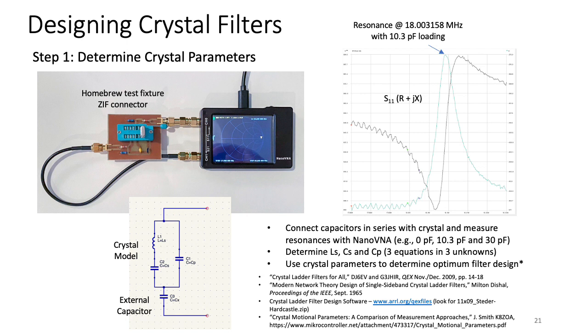Here's another example of a 2-port linear network, and this is a crystal filter in this case. However, in this case, what I want to do first is determine the parameters of the crystals so that using those parameters, we can design the ladder network. So to do so, I want to look at the crystal model, and the crystal model is shown here, which consists of a motional inductance, a motional capacitance, and a parallel capacitance, which represents the case and the connecting items to the quartz itself.